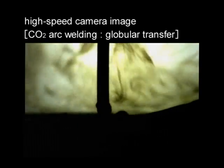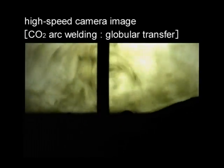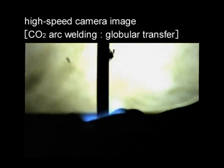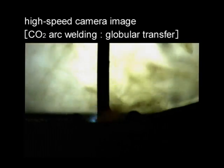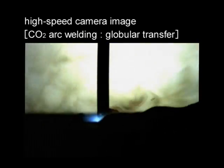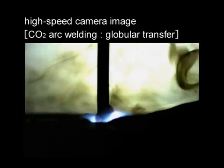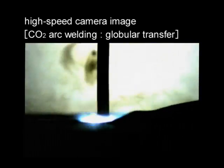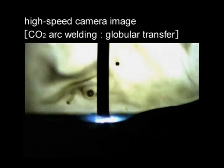In this mode of transfer, the wire generally does not short to the base metal, therefore the number of short circuits is less compared with that of short circuit transfer mode. Globular is in the range of 10 to 50 times per second. Therefore, the arc sound is loud and the arc is less stable. Large spatter balls can occur. However, higher arc energy is obtained.